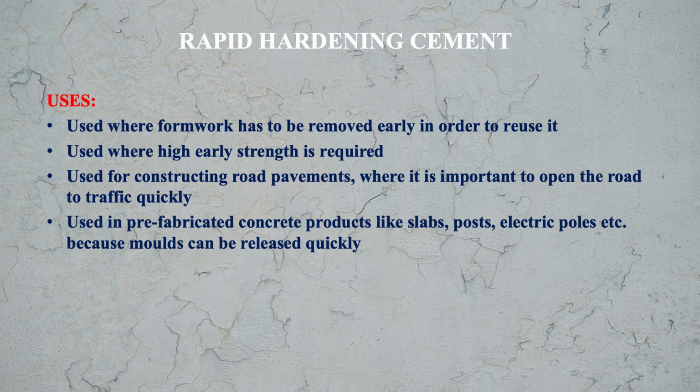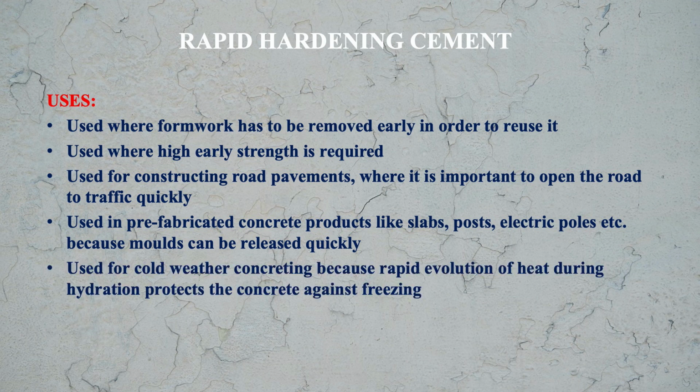One more use, we see that it can be used for the cold weather concreting, because rapid evacuation of heat during the hydration protects the concrete against freezing. What is the problem in cold weather concreting? Basically, that there, because of the low temperature, the water which we are using to make concrete, it becomes ice, it freezes.